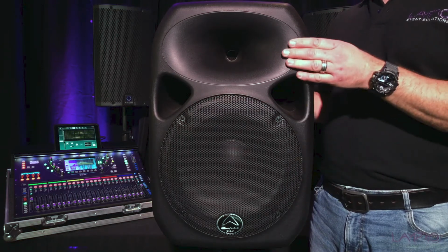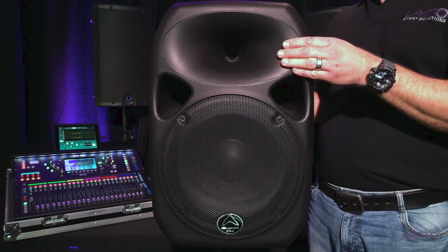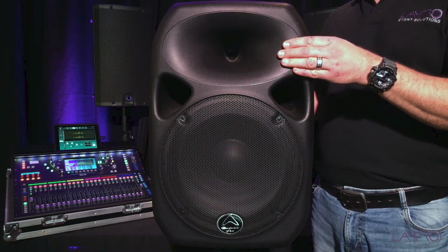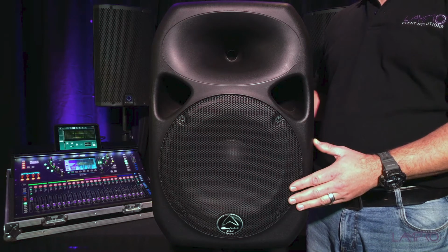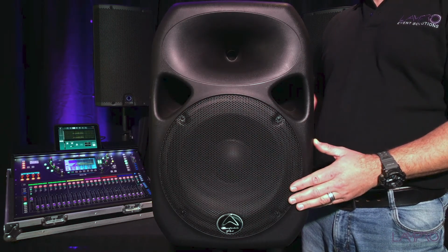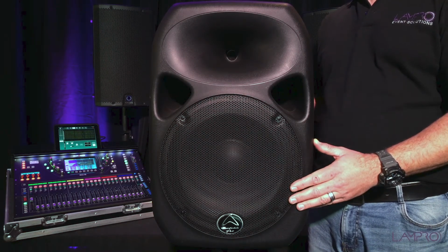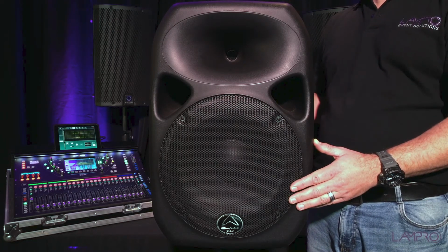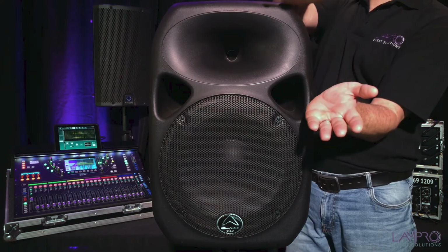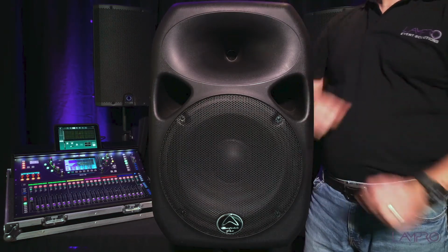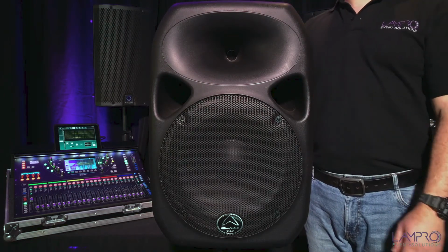The high frequency or compression driver produces your high frequencies from 500 Hz to 20 kHz. The low frequency driver or woofer produces frequencies between 55 Hz and 5 kHz. Point source speakers usually have an angle of 110 degrees horizontally and 45 degrees vertically that it can cover, so the right speaker placement is very important.